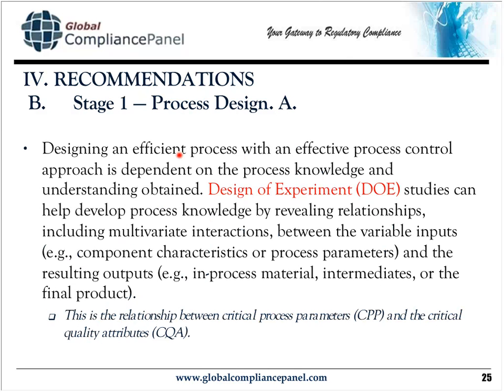And during your process design, you need design of experiment studies, DOE. Now, exactly what is DOE? If you're not familiar with the term, DOE refers to what are known as factorial studies. These are studies where you do many different factors or elements of your process, and you look at the outcome that happens as you make adjustments. And usually these are so-called two-level studies where you do high, low, plus, minus, etc., etc.